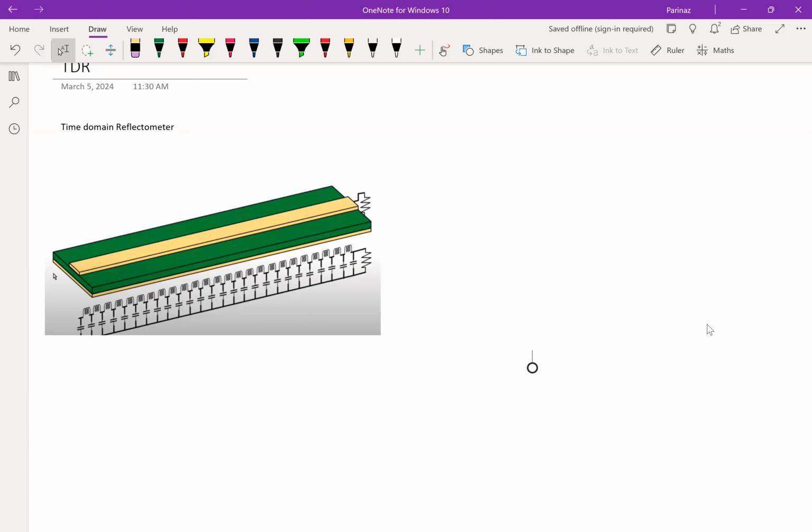So it's composed of two conductors, and they both need to be there, and they are usually separated with a dielectric. So for example, here, this is the conductor that looks like a trace, or basically a metallic rectangle with a certain thickness. And then this is the return path of it, or the ground for this. So this is conductor number 1, and this is conductor number 2. And they are separated with a dielectric slab, which is something that is non-conductive.